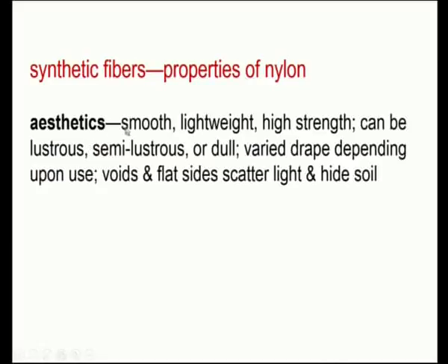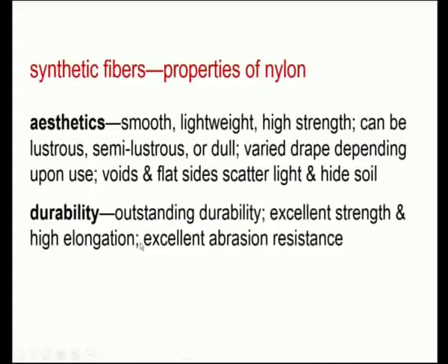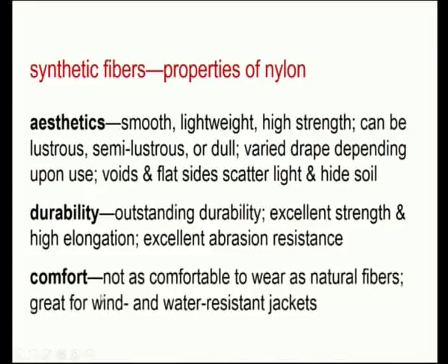Nylon aesthetics: it looks smooth, lightweight, high strength, can be lustrous, semi-lustrous or dull, with varied drape depending upon use. Wide and flat sides scatter light and hide soils, so it will not absorb soil material. For durability, it has outstanding durability, excellent strength, high elongation, and excellent abrasion resistance, so it has a very long life. For comfort, it is not as comfortable to wear as natural fibers, because synthetics have this kind of problem.